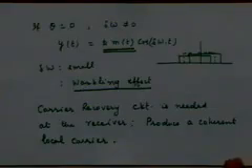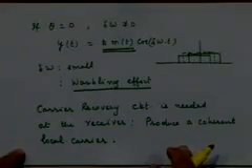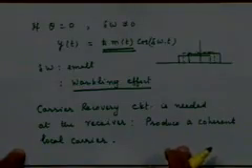So there are special circuits one has to make to carry out this carrier recovery operation, to make sure that your local carrier is in phase and frequency synchronism with the incoming carrier. And that's why a synchronous demodulator is typically a complex operation, because you need to worry about carrier synchronization. Okay.